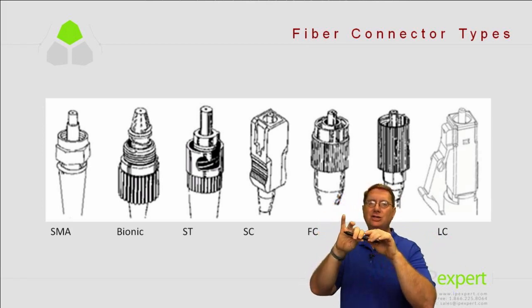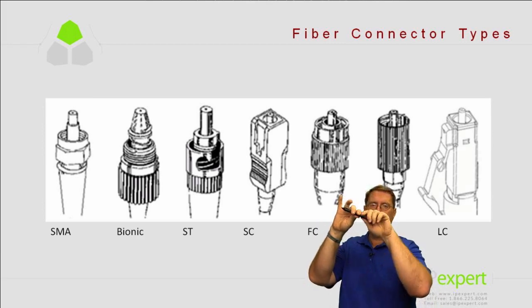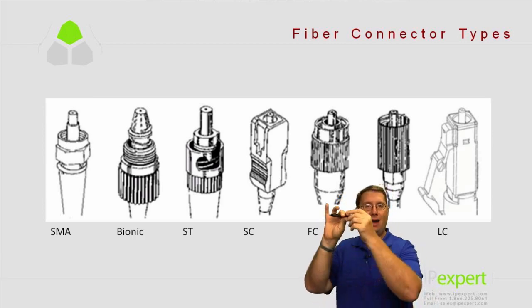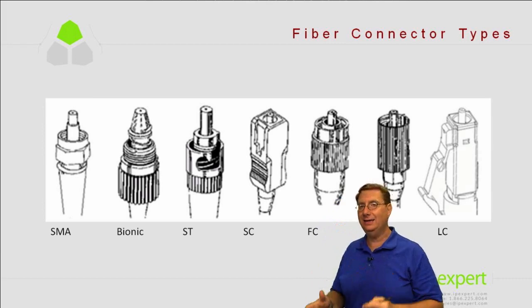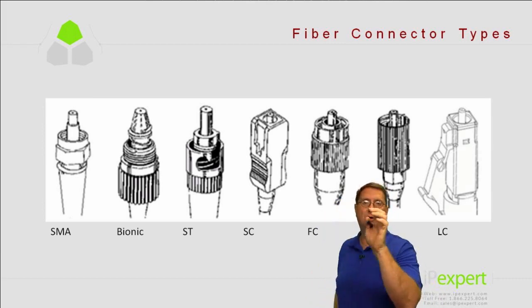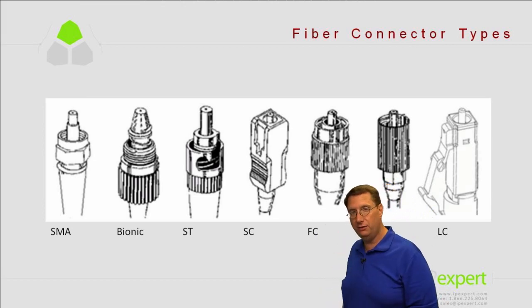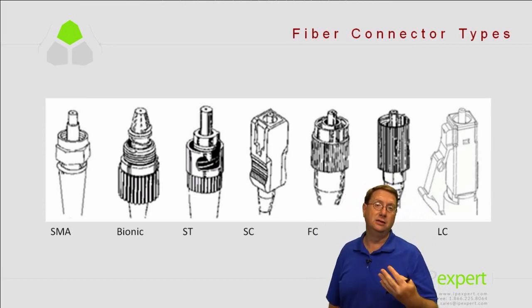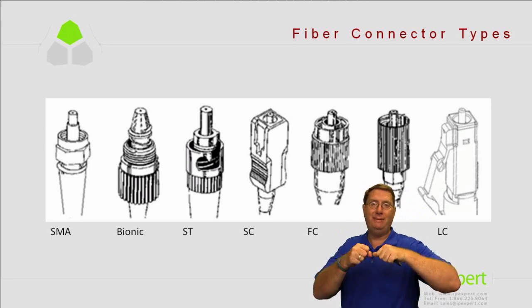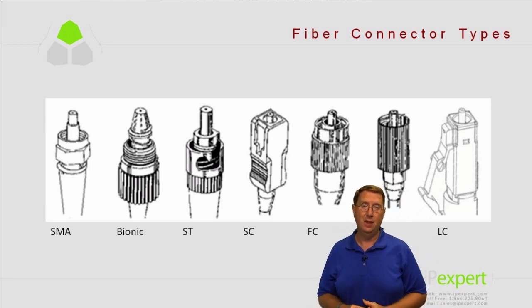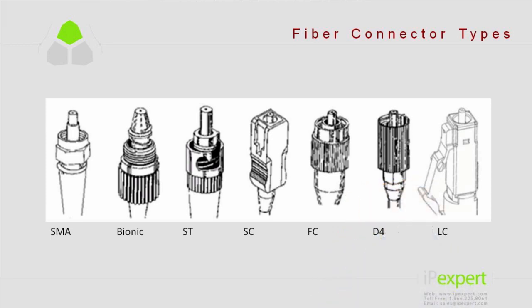And what happens is it actually separates those fibers a little bit, to where my bend is so great that light can escape. The light comes in, hits the corner and starts shining through, and then what ends up happening is I get degraded signal on the other end. So think of it almost like the light is being leaked out, because when I bend it, I place the cladding under strain. That's something that we definitely want to make certain that we avoid.